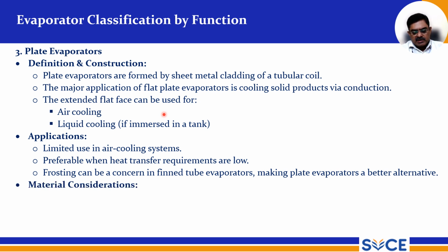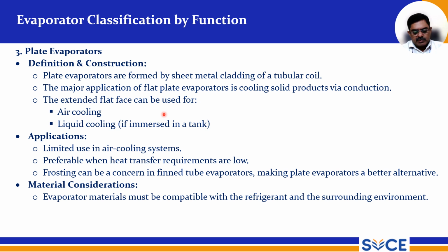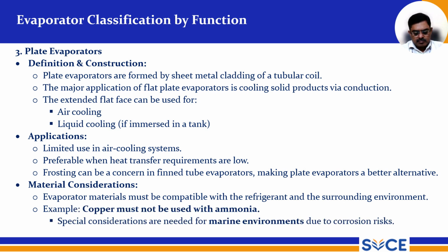So, material considerations here. Evaporator materials must be compatible with the refrigerant and the surrounding environment. For example, copper must not be used with ammonia. Special consideration is needed for marine environments due to corrosion risks.